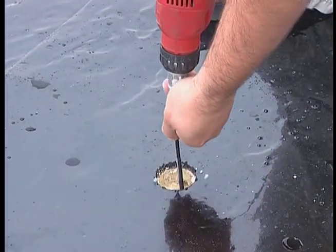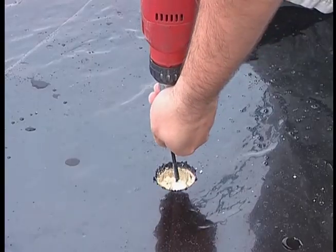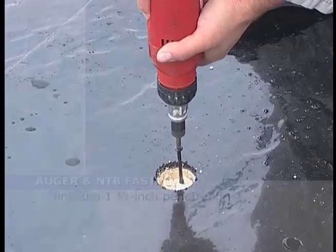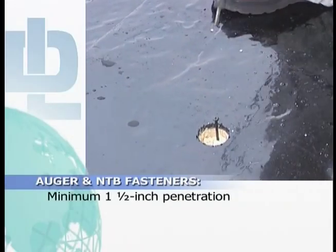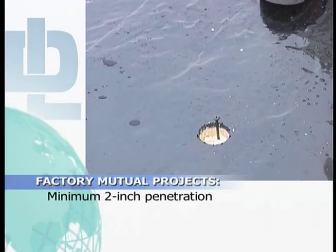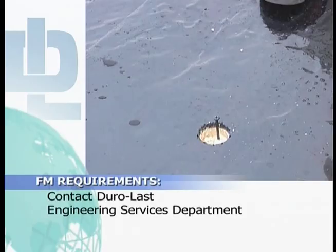Install an approved fastener into the roof deck, making a 1-inch penetration from the deck surface and leaving a minimum of 1 inch exposed above the roofline. Auger and NTB fasteners require a minimum 1.5-inch penetration. Factory mutual projects require a minimum 2-inch penetration. Contact the Duro-Last Engineering Services Department for more information on factory mutual jobs.